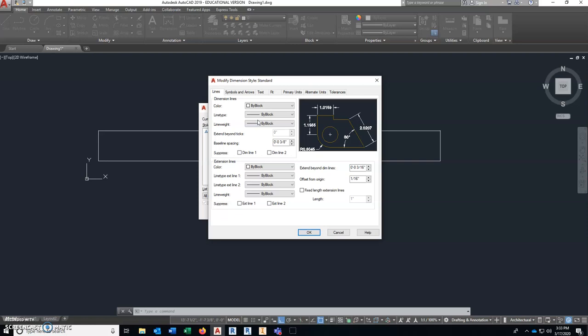So what I have to figure out is, because of my scale factor, I know when plotted, I like a 1/16 of an inch text. So I know that blowing a 1/16 of an inch up 48 times, I end up with a text height or a text size of 3 inches. And that's just doing some figuring.